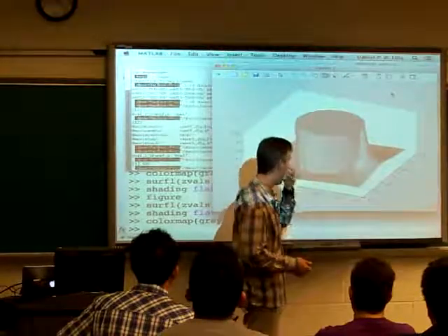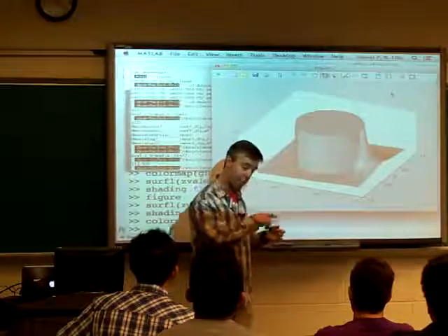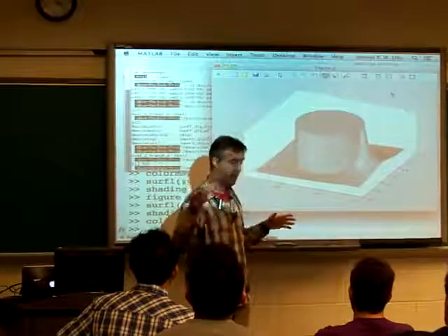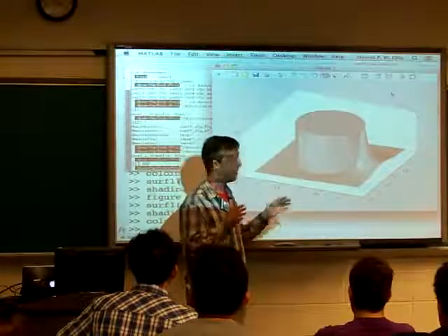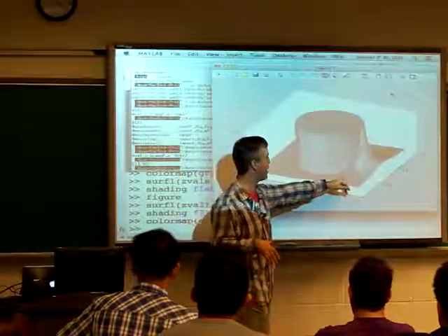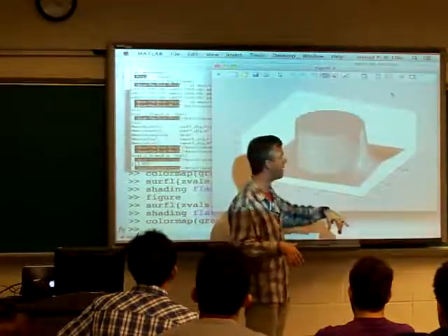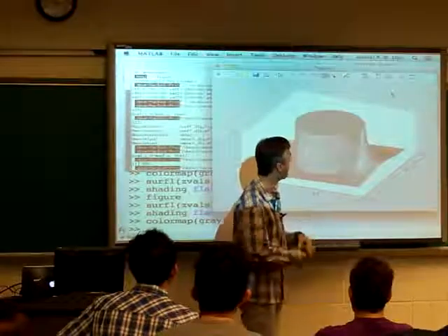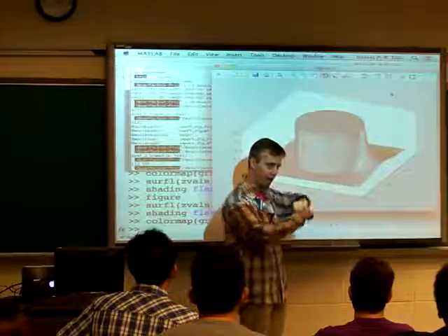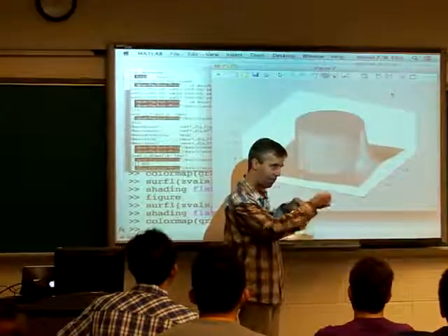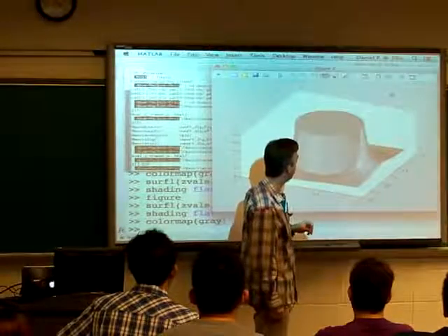imaginary part. I evaluated the sum of my sequence, which was a nice decaying exponential sequence, over 1,000 points, raising some value of z to successively negative powers of n, summed them up, and then I just stored that in an array. So this looks like a continuous surface, but actually it's like every 0.01 or something.